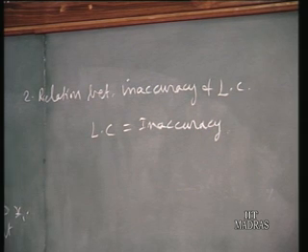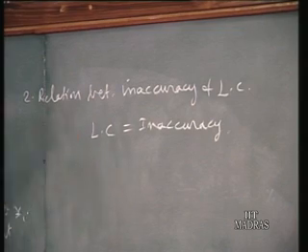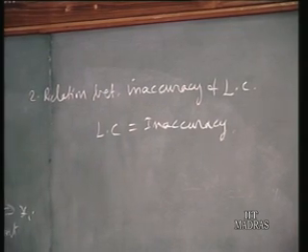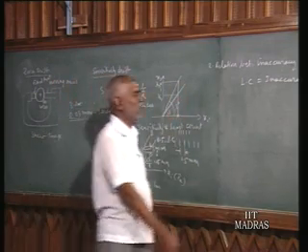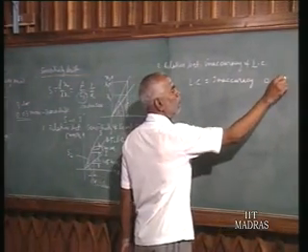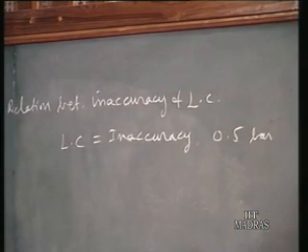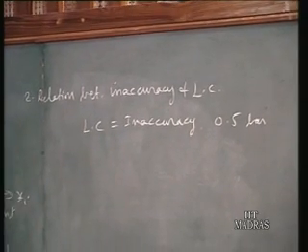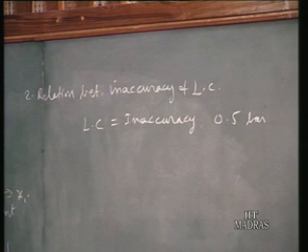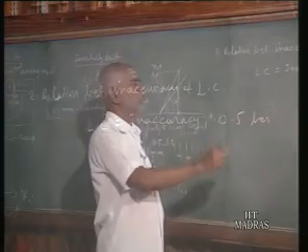That is how the instruments are designed. The least count is made so. If we find the sources of inaccuracy and add all the inaccuracies, you will get a certain amount of inaccuracy. Say probably here I got 0.5 bar as the inaccuracy for that particular pressure gauge. Then make that maximum inaccuracy itself the least count. This is the principle normally adopted by all manufacturers throughout the world. So, in case you have lost the pamphlet, don't bother. Find out the least count of the instrument, and take that least count itself as the inaccuracy.